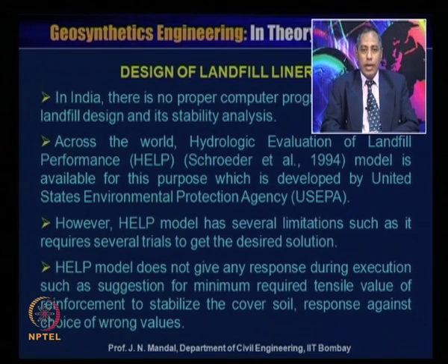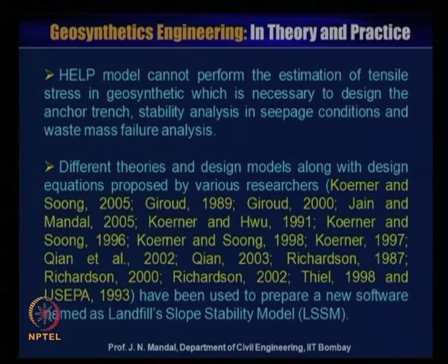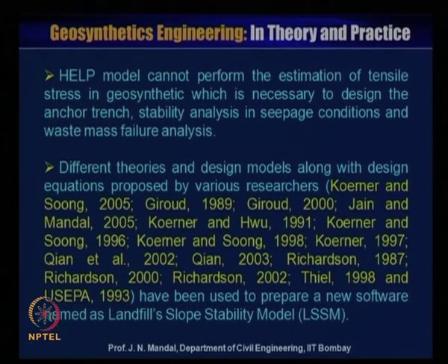The HELP model does not give any response during execution, such as a suggestion for the minimum required tensile value of reinforcement to stabilize the covered soil, or a response against the choice of wrong values. The HELP model also cannot estimate tensile stress in geosynthetics, which is necessary to design the anchor trench, for stability analysis in seepage condition, and for waste mass failure analysis.